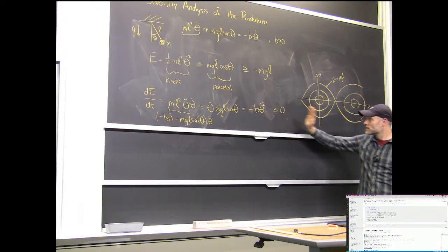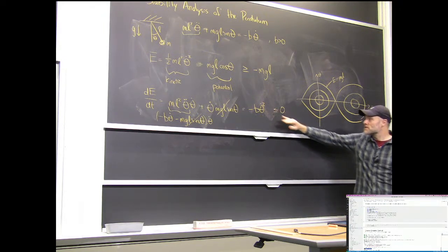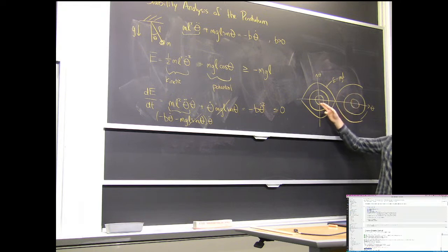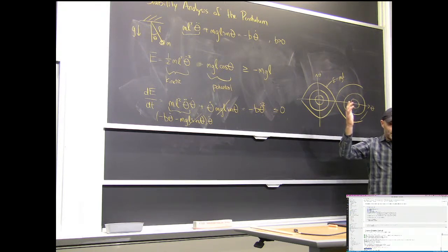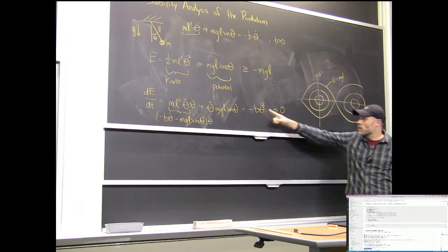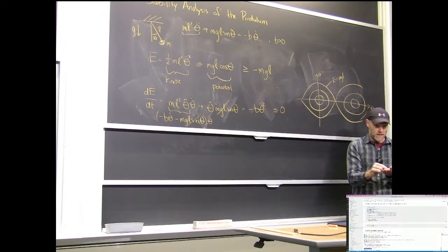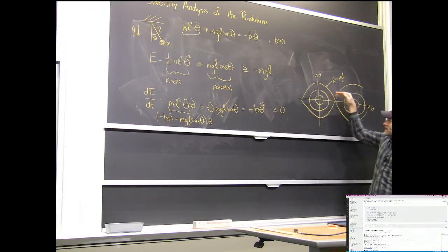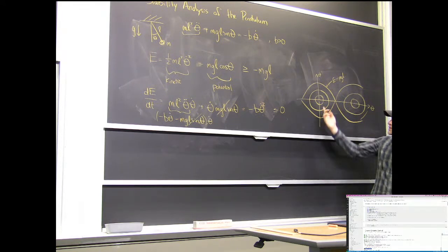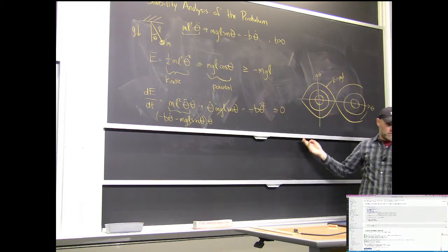Okay? So let's think of the easy case first. Let's say that was strictly less than 0. Do you understand the argument that I'm in a bowl? That bowl is defined. I'm saying I'm always getting smaller in the bowl, except for when I get to the bottom, that would mean theta dot equals 0, and I'm at the bottom and I stop. So I'm doing gradient descent on this bowl effectively, a form of gradient descent. At least I'm going downhill, and I'm going to get to the bottom. That's a way to certify the stability of this with equations that's going to scale. That idea is going to scale to much more complicated systems.